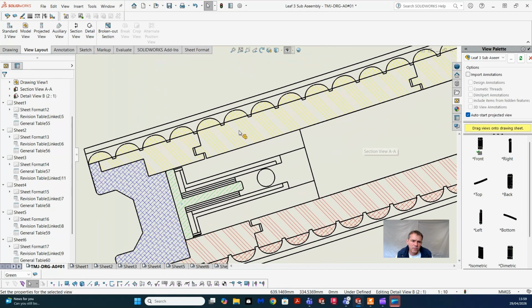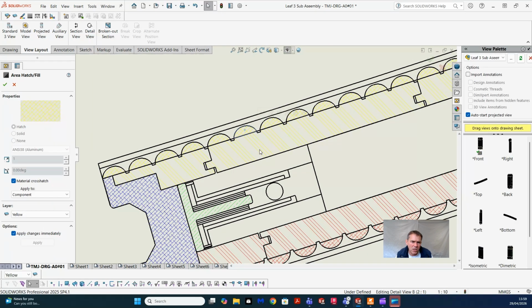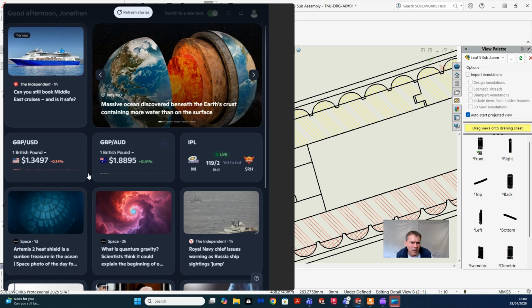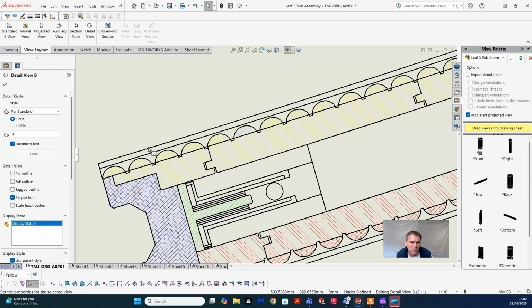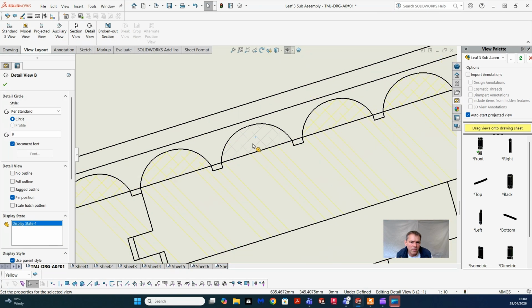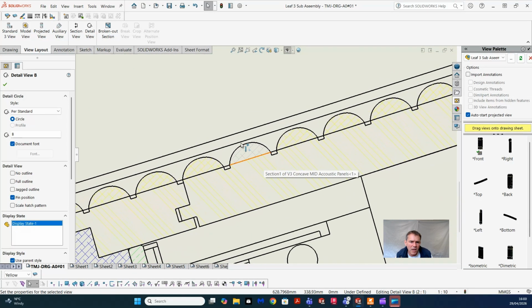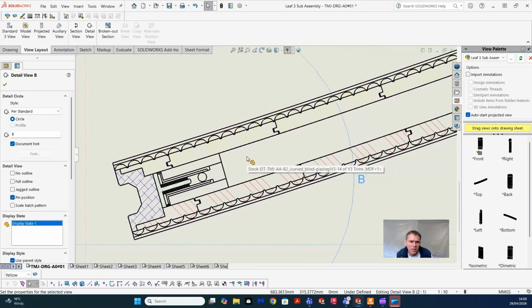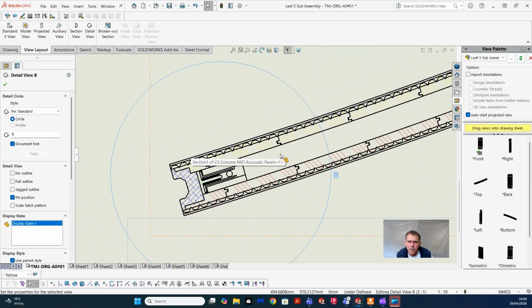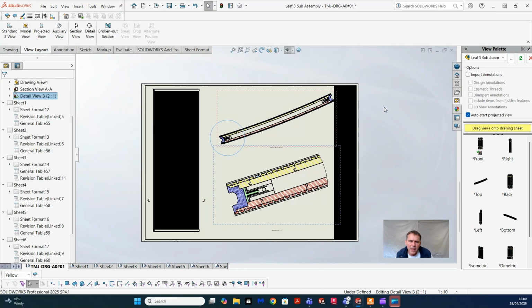And then let's just say that you wanted to change this body individually, just to let you see how this works as well. Let's say we want to apply it just to a body, and we want just that body to be, well, let's turn it light grey, shall we? Light grey, click off of that. You can see it's gone light grey. So once you've ticked that default box, you don't need to do it again, and that particular body's gone light grey, and it's gone light grey in here too. Okay, so that's great. And that all works really, really well.